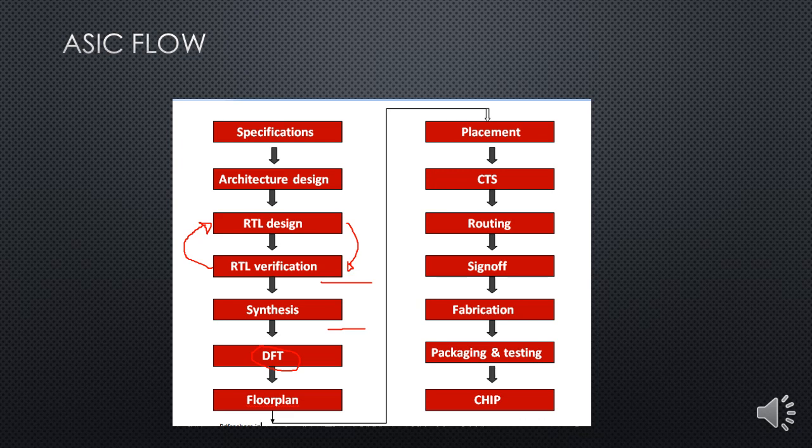In that die we can develop some thousands of ICs. So out of the 1,000 in that lot, how many of the transistors are working? If out of the 1,000, 800 are working, we can say we have 80% yield. Or else, for example, say out of 1,000, none are working. That means something is wrong in the fabrication step itself.